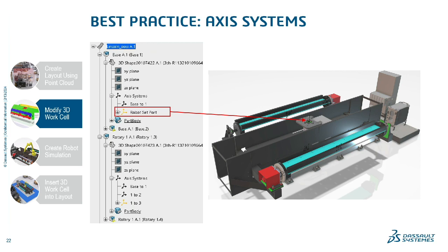And why I say that is, since SOLIDWORKS owns the CAD data, it owns the design data. You can't modify the design data in the 3D Experience platform if it is not the CAD owner. So what you would have to do is create more 3D shapes, and oftentimes not where you want them, and you're messing with your design data at that point, which isn't what you want to do in this application.